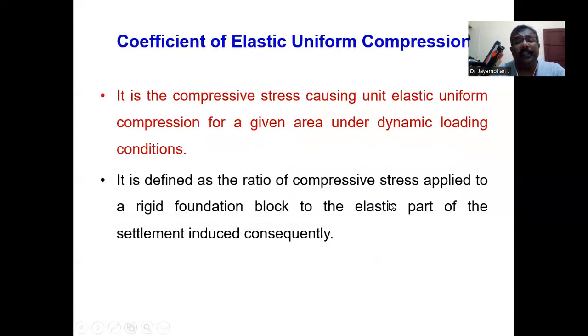And here we have discussed a parameter called the coefficient of elastic uniform compression. It is the compressive stress causing unit elastic uniform compression in a given area under dynamic loading conditions.